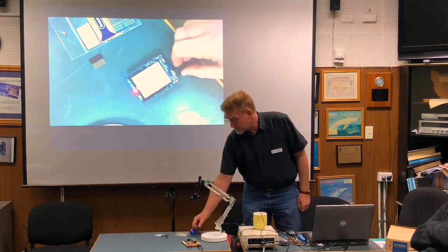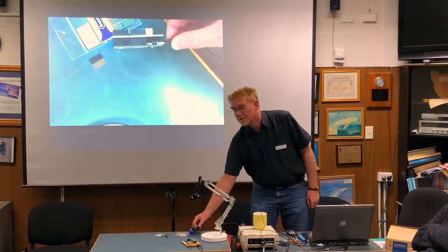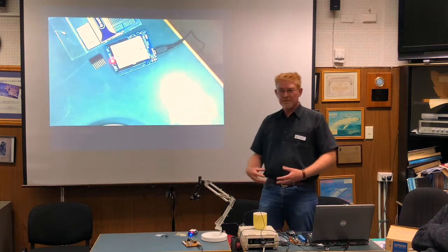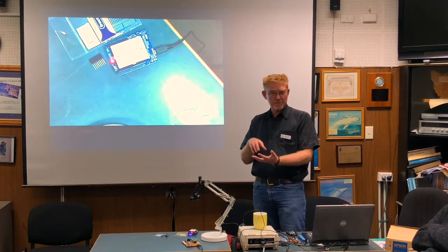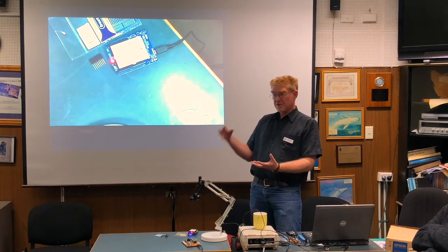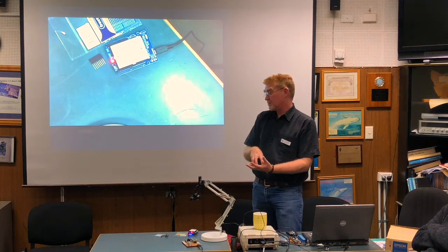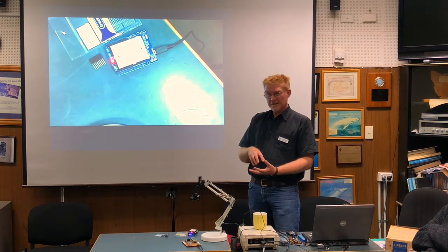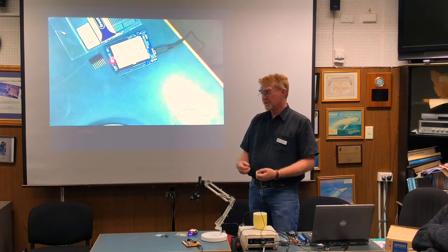The other cool thing you'll notice is that these things stack. So you can actually have breadboards on breadboards on breadboards. I've seen people do projects where you'll have the Arduino, a shield with a micro SD card holder on there so you can put some expanded memory in, and maybe a GPS module on top of that, and maybe, I don't know, a cellular modem module on top of that. It starts getting a little bit complicated, working out what all these pins are being used for, and whether they're going to conflict with each other.